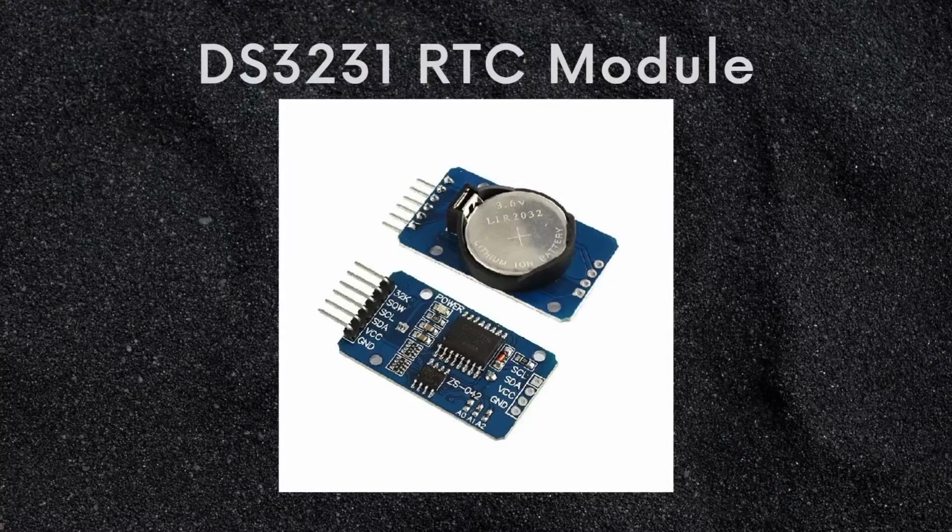The date at the end of the month is automatically adjusted for months with fewer than 31 days, including corrections for leap year. The clock operates in either 24-hour or 12-hour format with an active low AM/PM indicator. Two programmable time-of-day alarms and programmable square wave outputs are provided. A precision temperature compensated voltage reference and comparator circuit monitors the status of VCC to detect power failures, to provide a reset output and switch to the backup supply when necessary.